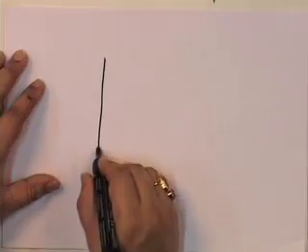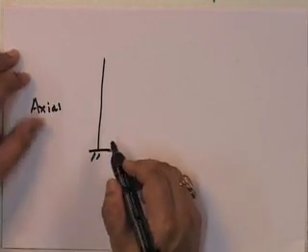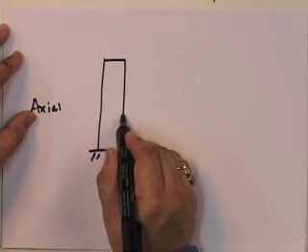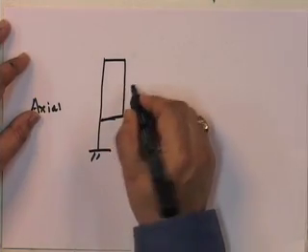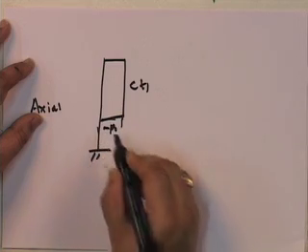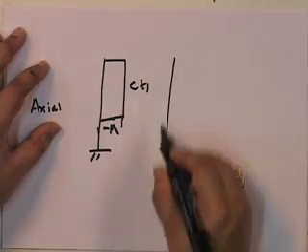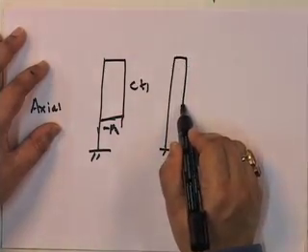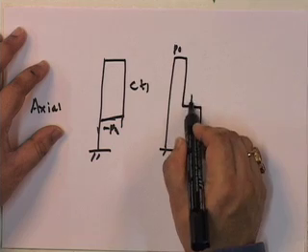If you look at the stress wave, what I call the axial force wave, the axial force wave looks like this. The axial force is a constant, right? Axial force is a constant, and this is CT1, and the entire thing is P naught. So, the wave that comes is P naught. Then you have a situation where you have P naught and P naught.